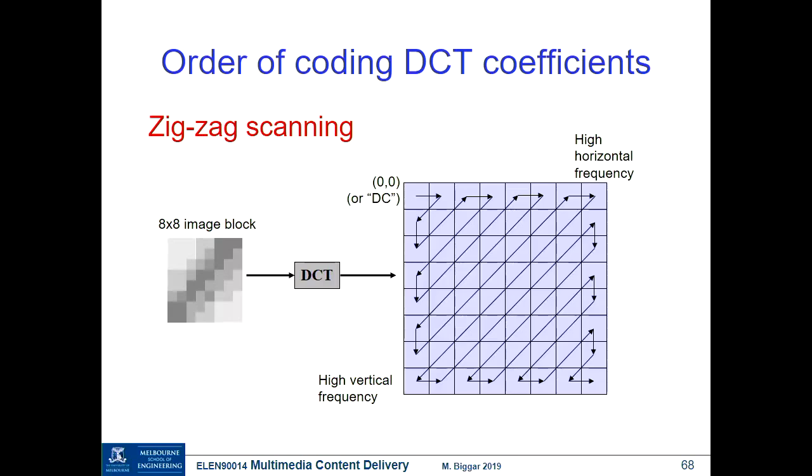Yeah, very good. That's exactly right. Because we've seen that the result of the DCT is to push all the energy up into this top left-hand corner. It's not to the top line, it's in the top left-hand corner. So all of these coefficients out here, particularly when they're quantized, are going to be very small or zero. So by reading out these coefficients in this order, partly we encounter the larger magnitude ones earlier, but most importantly, we'll get to the last non-zero value earlier. So we can just reserve a special code saying end of block.